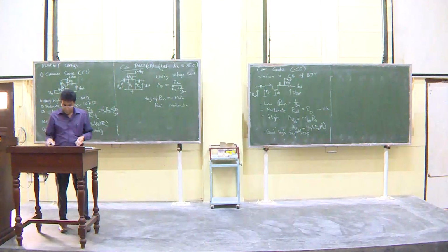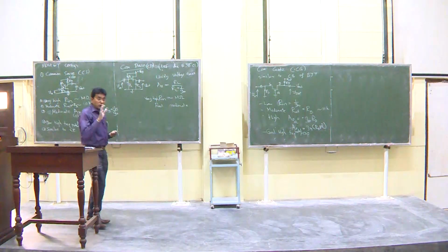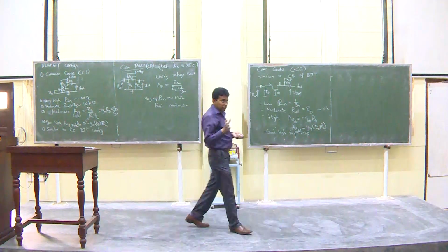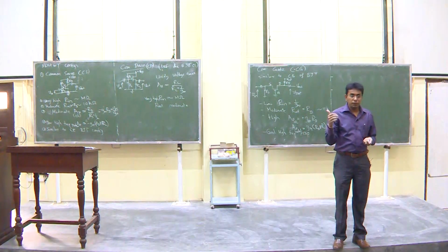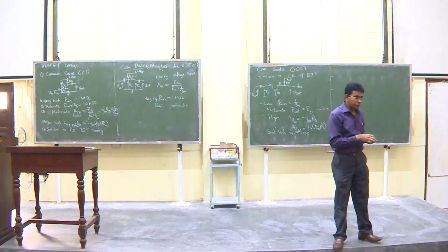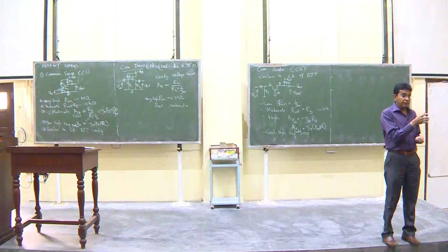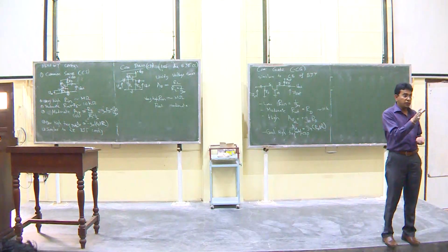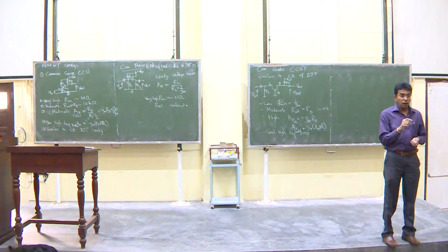Right, so these are the configurations, the BJT and MOSFET configurations that we have. In general, MOSFETs have higher input impedance, much faster, but can only handle lower levels of currents.